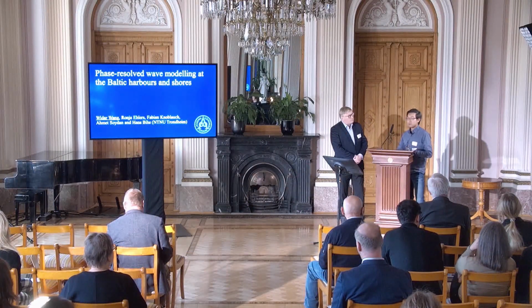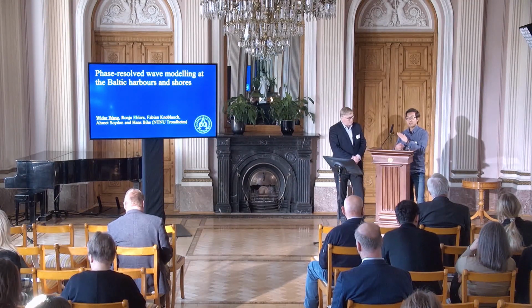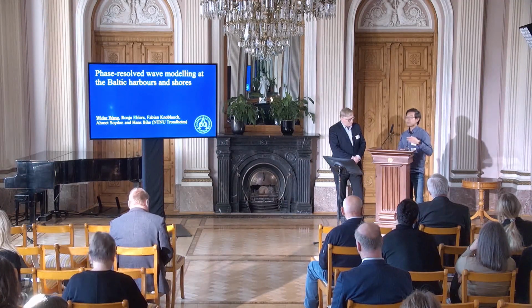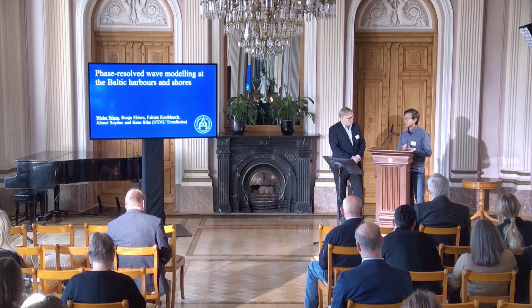That's a very good question. I think there are two, probably three, main differences between the Norwegian harbor and the Baltic harbor. In the Norwegian area, because of the existence of fjords and a lot of harbors along the fjords, the water depth changes more drastically. You can have an almost 45-degree subsea slope outside the harbor. You move out 500 meters, and you already have 500 meters of water depth. So that's a very drastic change.